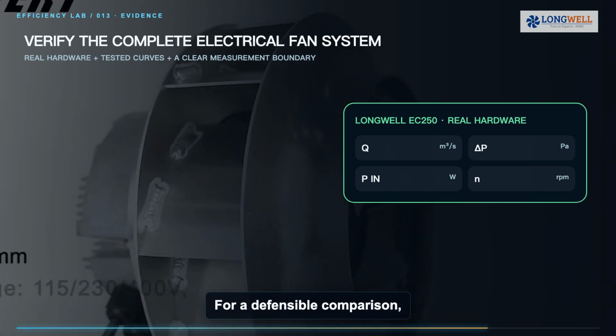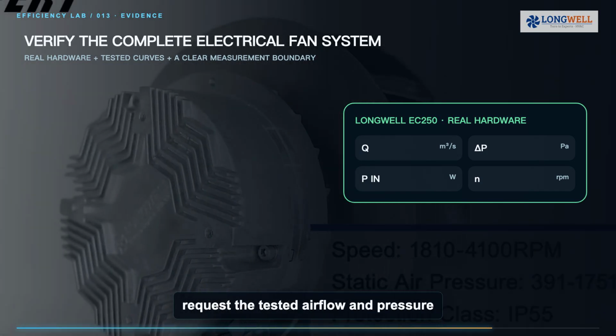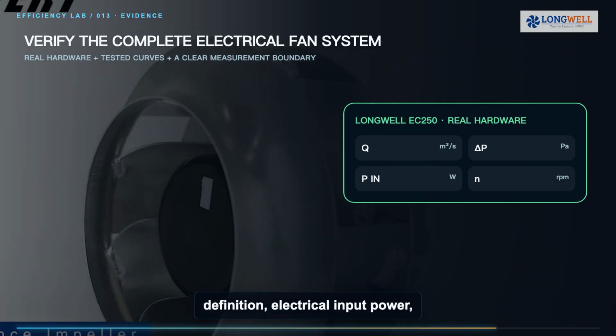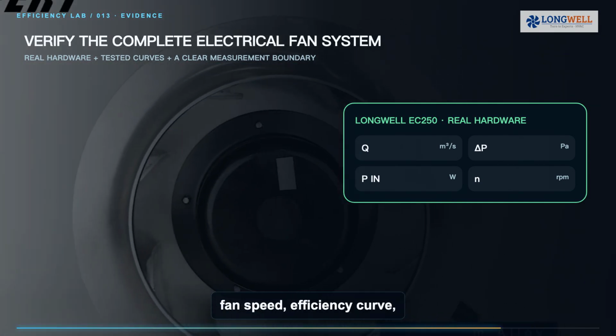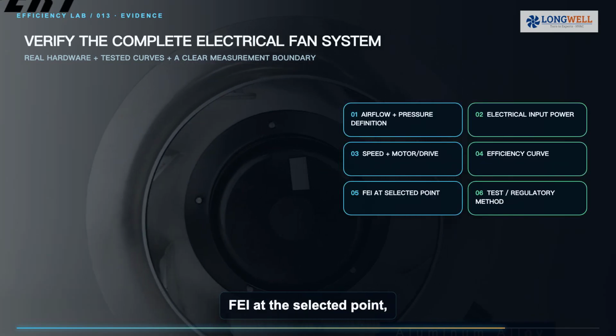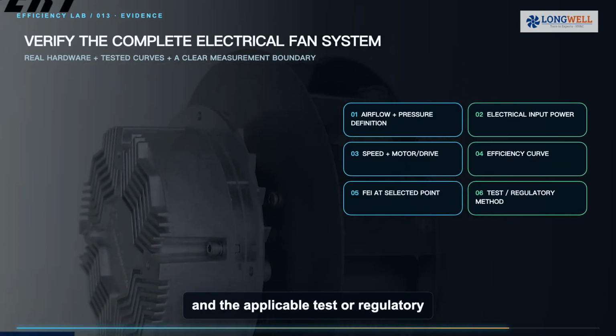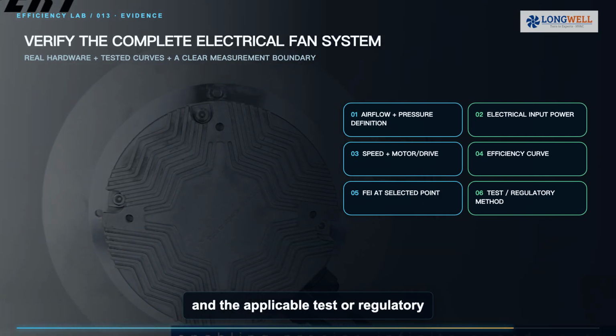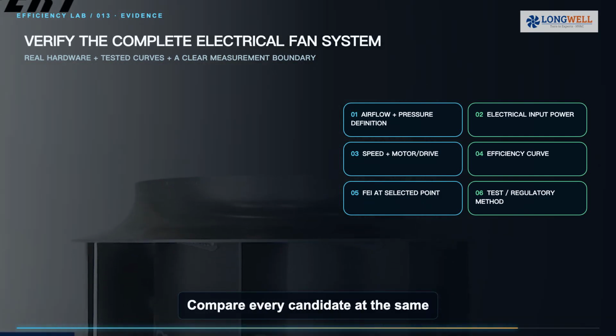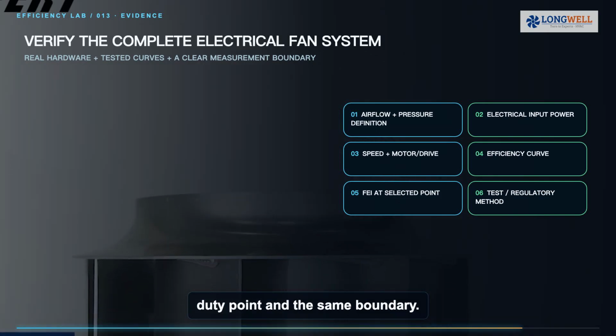For a defensible comparison, request the tested airflow and pressure definition, electrical input power, fan speed, efficiency curve, FEI at the selected point, motor and drive configuration, and the applicable test or regulatory method. Compare every candidate at the same duty point and the same boundary.